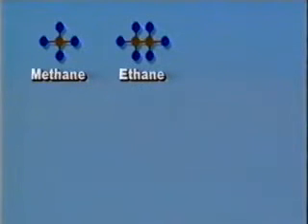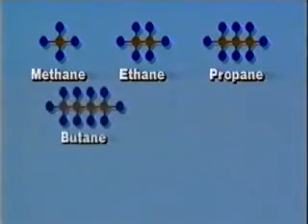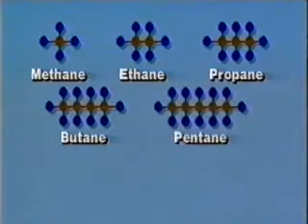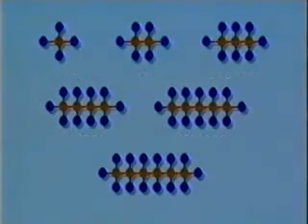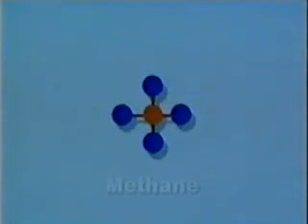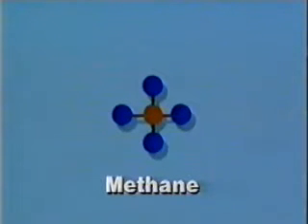So, listed from lightest to heaviest, the components of natural gas are methane, ethane, propane, butanes, pentanes, hexanes, some heavier components, and liquid condensates. Methane is the lightest hydrocarbon gas, and it often makes up the highest percentage of the natural gas. This gas, mixed with some ethane, is a typical gas which reaches a transmission line for sale.